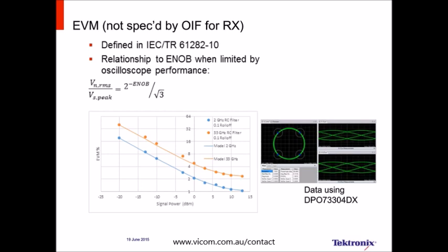So now shifting gears for a second, talking about measuring the properties of a receiver, these specs, looking back at the OIF documents, are mostly frequency domain specs. They include total harmonic distortion, 3 dB bandwidth, common mode rejection ratio. These are all things that are measured in the frequency domain. And EVM is not one of those because EVM really comes from all of those other measurements. But if you'd like to measure EVM directly, then this is a nice way to do it: just put in a heterodyne signal and then demodulate it as if it was a QPSK signal. Because there's no modulator there, there's not going to be any modulation error, and so the error you measure is from the analyzer itself.